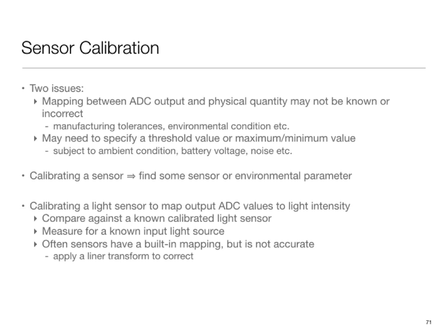The challenge here is that the calibration values vary from sensor to sensor for the same type of sensor, and they vary over time. So that leads to the problem. It's a little bit like the problem we faced in crystal oscillators with clocks, which is there were manufacturing issues and then there were issues over time which were a function of environmental conditions, aging, all those kinds of factors.